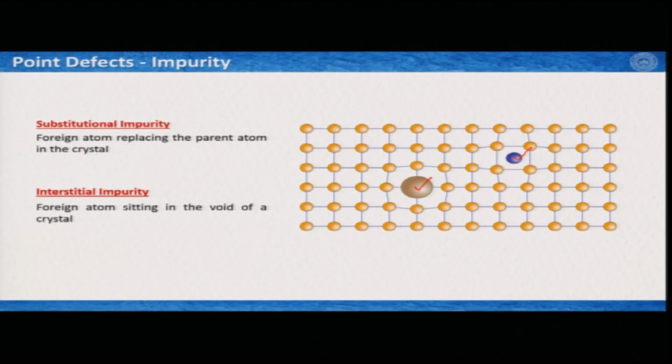Now, for the interstitial impurity, you can think of the carbon steels, most of our soft steels that we use nowadays, including in our cars and so on. The carbons are doped inside the ferrite crystals, which is a BCC crystal, and you can think of a carbon atom inside a ferrite crystal. So, carbon steel is a perfect example of interstitial impurity.